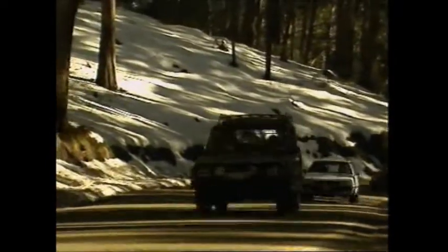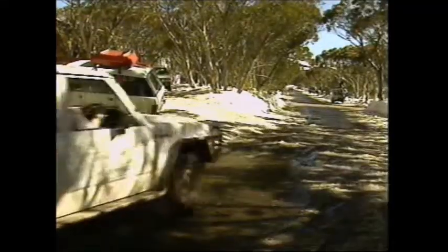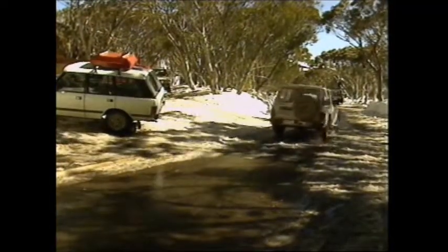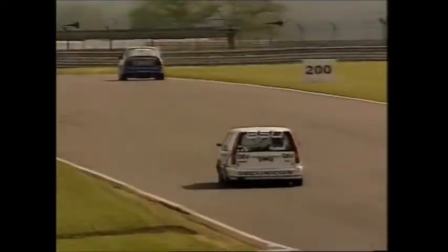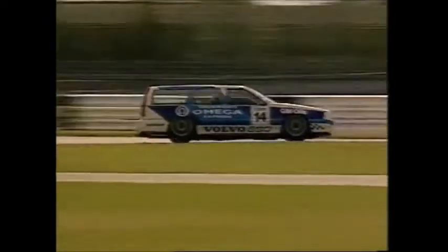Control of a vehicle in any weather conditions depends finally on frictional forces generated between the tyres and the road surface. On a dry road, a smooth rubber surface can provide a high coefficient of friction, sufficient to maintain a degree of control during braking, accelerating, and cornering. In wet conditions, the coefficient of friction between a smooth tyre and the road surface falls to an extremely low value.